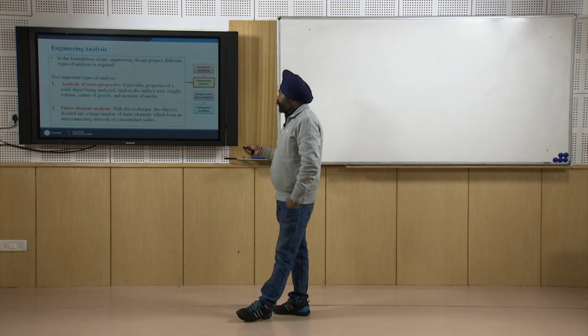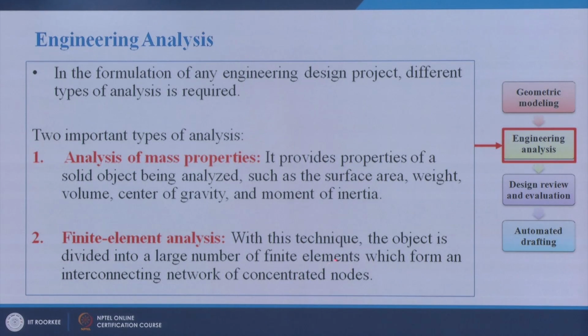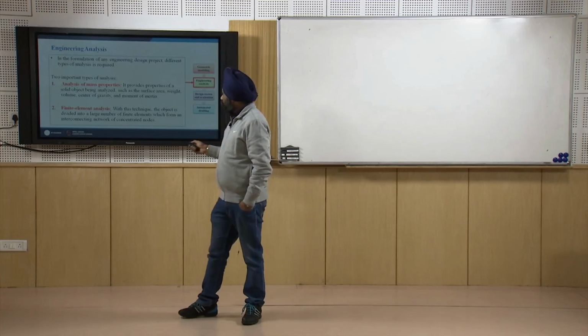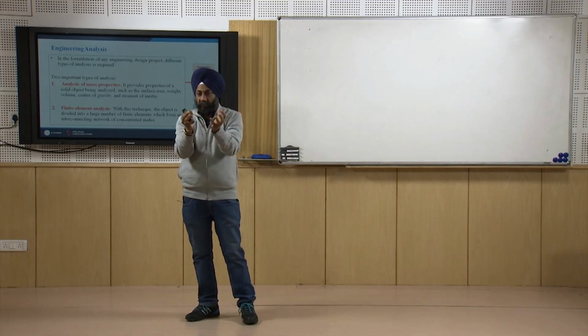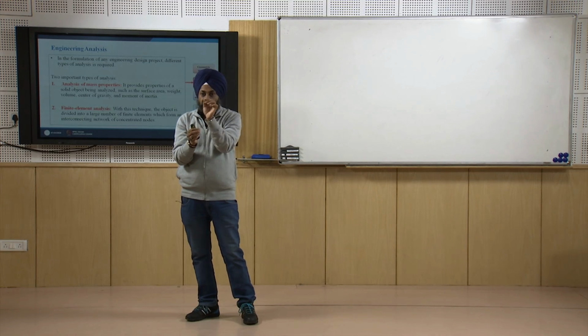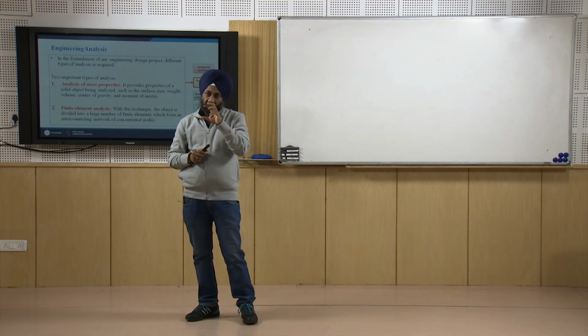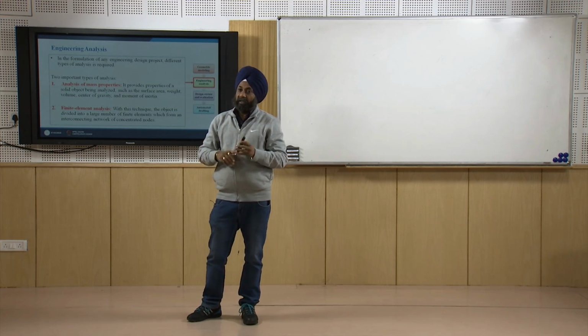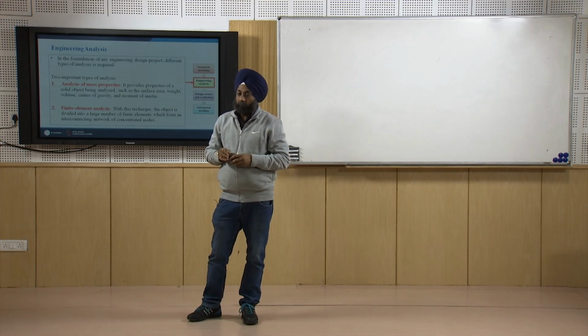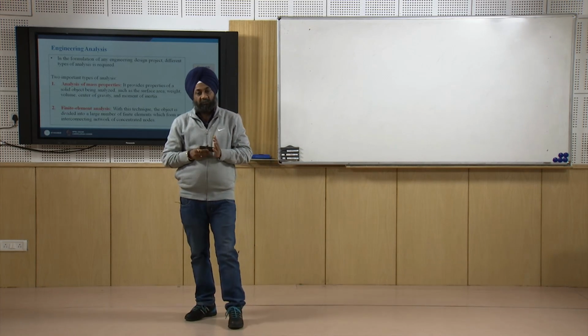With this technique, the object is divided into a large number of finite elements which form an interconnecting network of concentrated nodes. So we can divide the complete structure into its individual components or smaller finite elements, and then apply the boundary conditions. For example, we want to solve a cantilever beam problem.